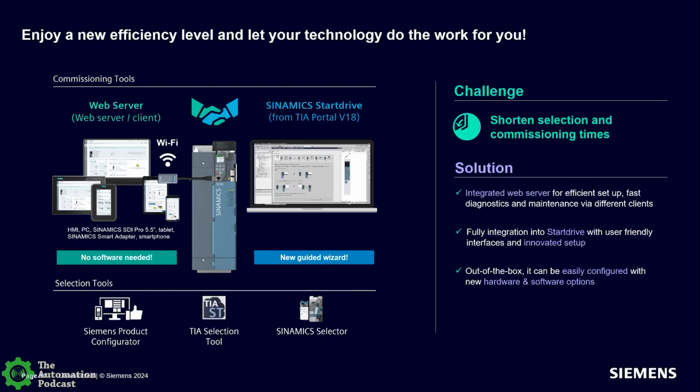Sure. Yeah, another good use of that smart adapter is, if I've got a drive in a cabinet, I can power that down, install this smart adapter, close the doors and power things back up without being in all of my protective gear, because I've got my enclosure doors shut now. Now I can access that product while it's fully protected and I'm not in all my gear. So that's another neat little way to use that product.